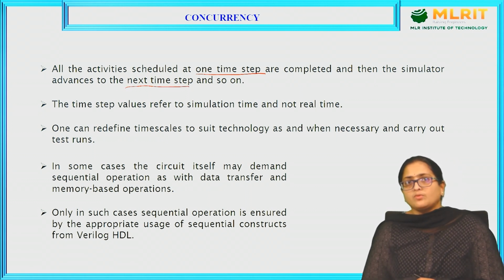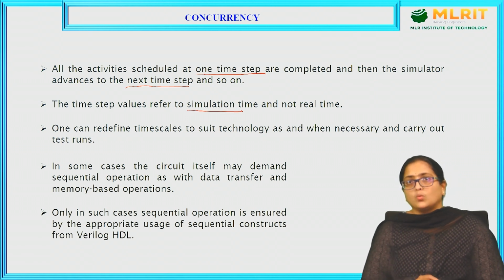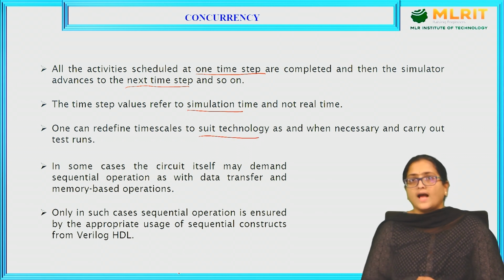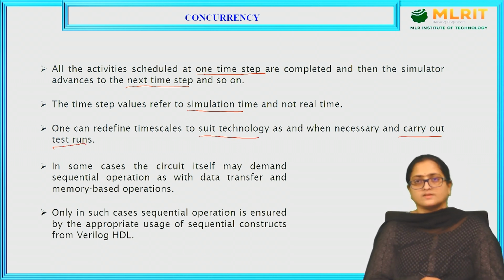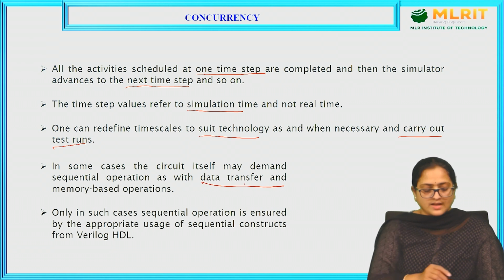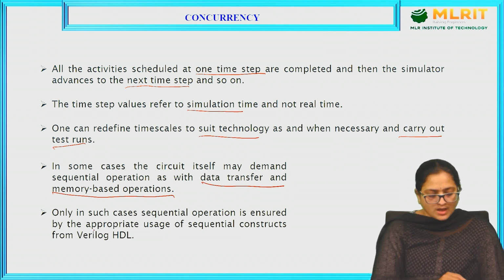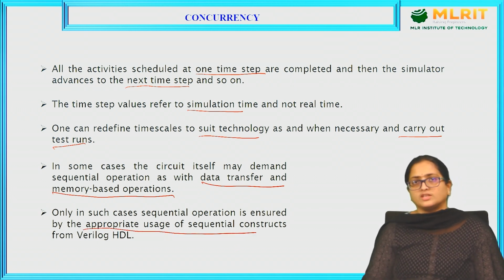The time step values refer to simulation time, not real time. One can redefine the time scale to suit the technology as and when necessary, or carry out test runs. In some cases, the circuit itself may demand sequential operations, as with data transfer and memory-based operations. Only in such cases, sequential operation is ensured by appropriate usage of sequential constructs from the Verilog HDL.